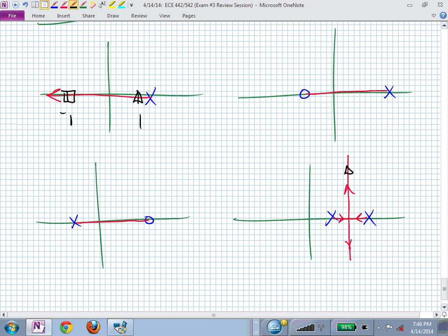You need to know something about the gain in your system, don't you? What's in the numerator? You now know the pole factors. You don't have any finite zeros, but you would have to know the scaling amount, wherever that was located. You might have a number in the denominator. I might give you the DC gain.